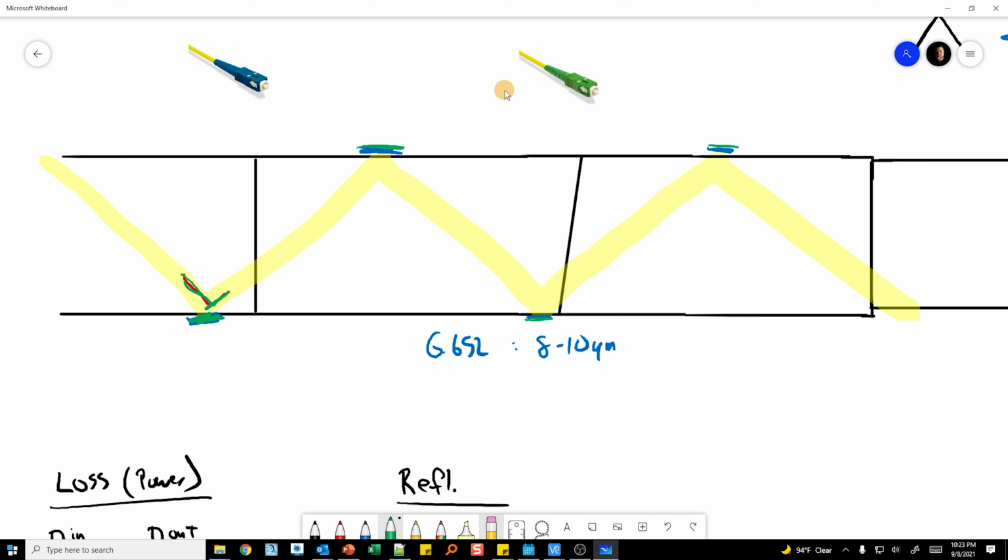And then, of course, as the signal travels across the fiber, when it goes across a connector, you're going to have some sort of loss. When it goes across a splice, you're going to have some sort of loss. Absorption within the glass itself and scattering are going to add to attenuation. So as the signal propagates, we start attenuating and get loss. For most standard single mode fiber at 1550, it's roughly 0.19 to 0.2 dB per kilometer of loss, roughly. There are different types of fiber, such as ultra low loss, so this is just a baseline here. This is what's happening here.